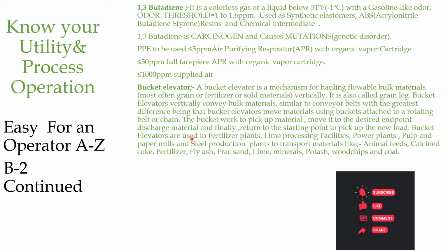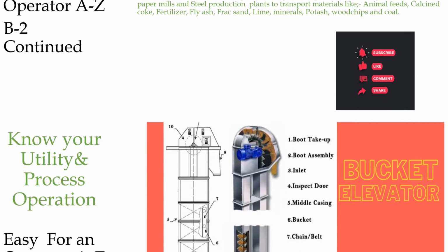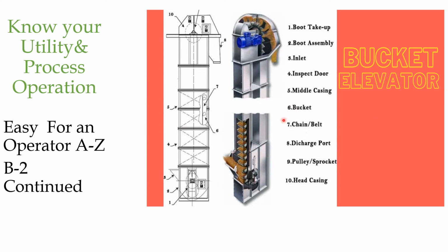We will see the schematic diagram of a bucket elevator in the next slide. This is a schematic diagram of a bucket elevator. You can see this is a boot. Normally, if it is a fine material or powder type material, it will collect in the boot. You have to clean it frequently. The boot assembly you have to open here,